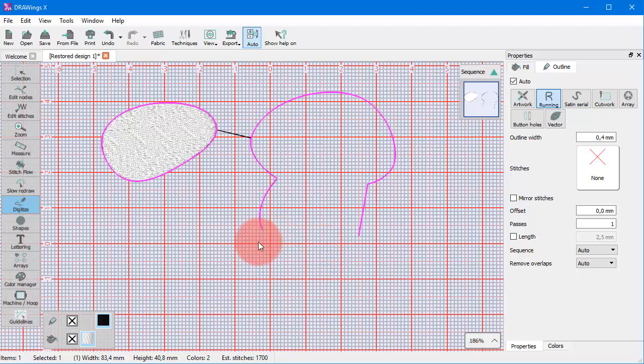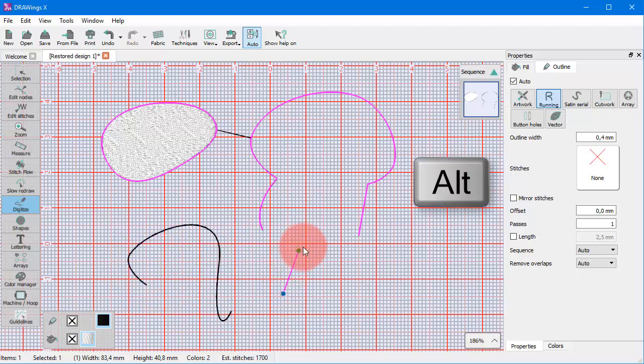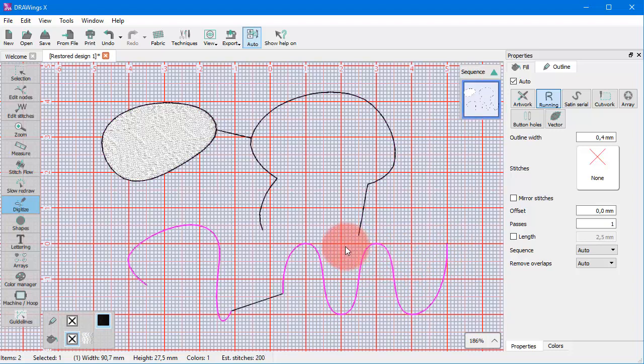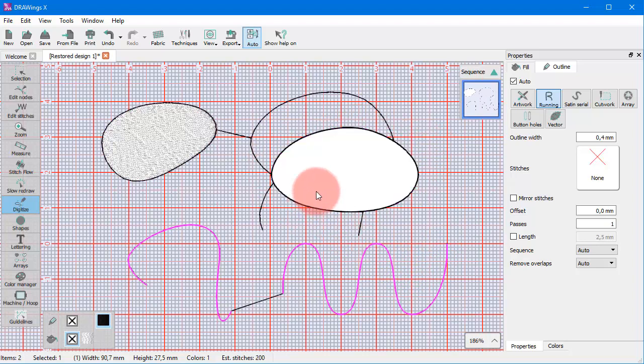While drawing, you can also click and drag to further edit the created curve. If you hold the Alt key pressed down, the mouse cursor snaps on the grid for your convenience. Finally, have in mind that you can easily create holes if you create any closed shape section on top of another.